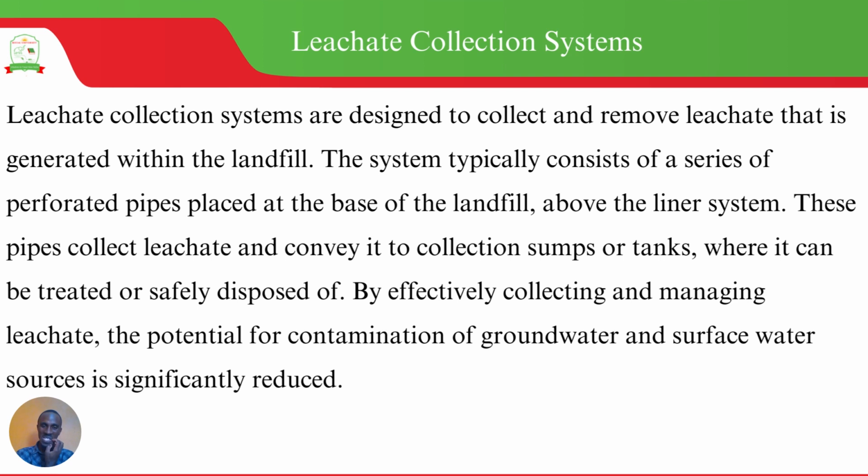Then we have leachate collection systems as one of the engineering systems that are put in place to protect the landfill. And these are designed to collect and remove the leachate which is generated within the landfill. They consist of a system of perforated pipes, like you will see in a visual that I've put in, and these pipes are placed at the base of the landfill above the liner system.